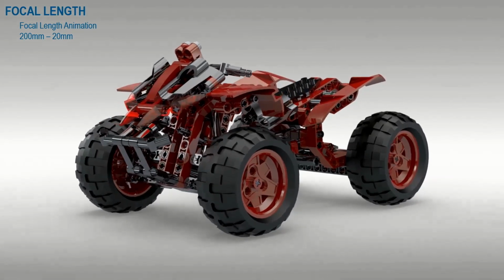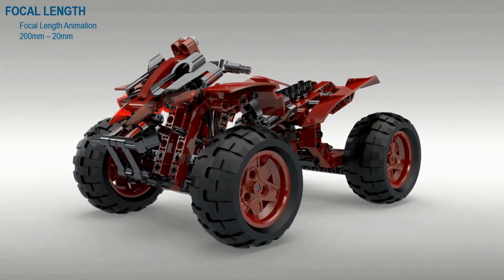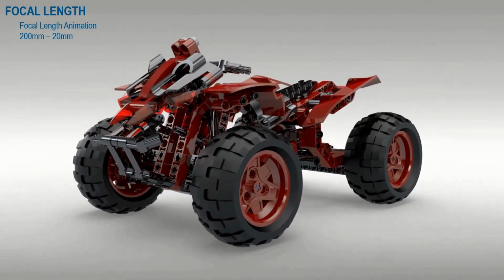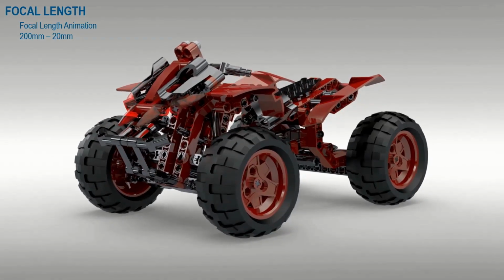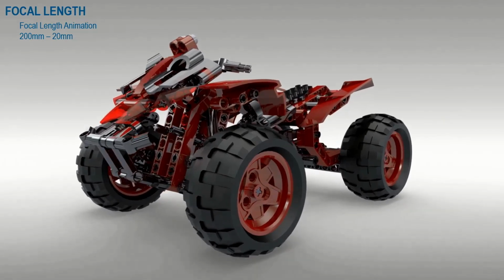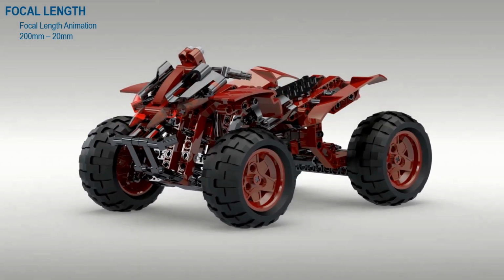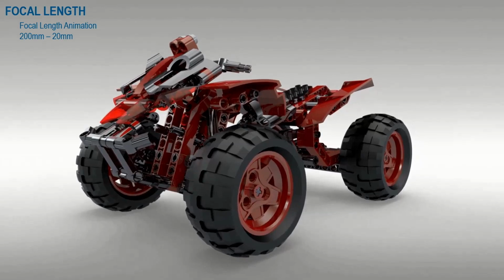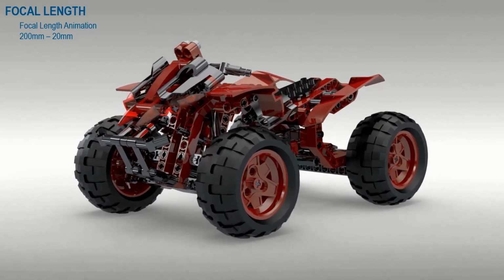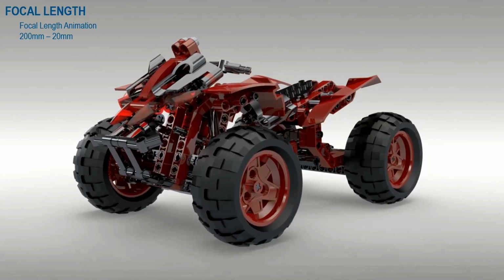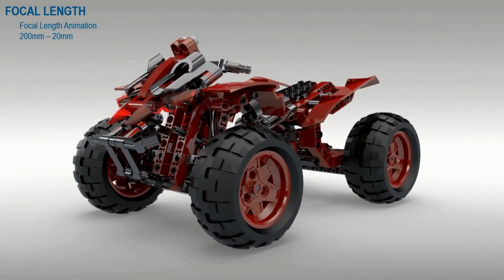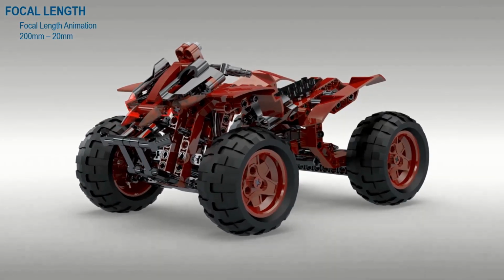So you can use the focal length to creative effect if you want a little bit more of an aggressive kind of up close image. A wider angle lens might make more sense, right? If you're looking for something that's more flat, ortho view, doesn't have a lot of perspective in it, then a zoom lens would make better sense. For that matter, you can turn off perspective altogether. You can just do ortho if you want, but usually when we're rendering, we want some sense of realism, so you want some perspective in there. But the lower the focal length, the more perspective you're going to get. It will also look further away, so you're going to have to move your camera up a little bit too.